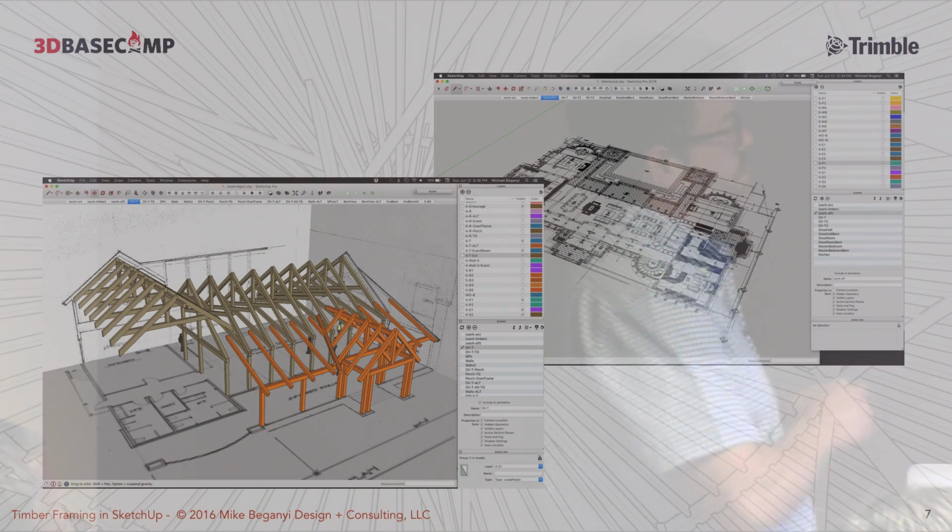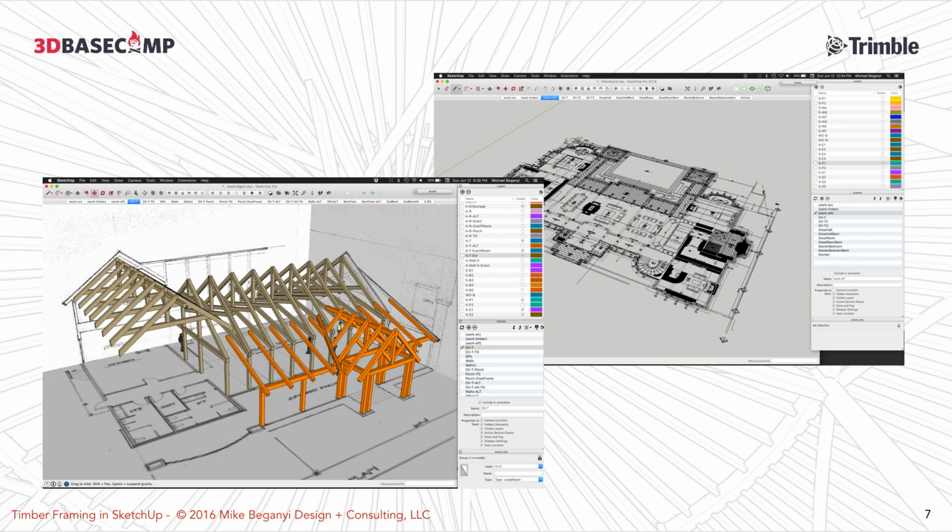Typically, if I'm working with another architect or engineer, I'll bring in CAD files, or in this case, hand-drawn. I didn't know people still did this, but they do. People still draft. He sent me scans, they would have been 24 by 36 scans of pencil drawings of this project here in the corner. I worked on that 2 weeks ago. I brought them in, and in SketchUp you can scale that if you have a known dimension using the scale tool. So I'll bring in whatever resources I have, and then I'll start modeling.